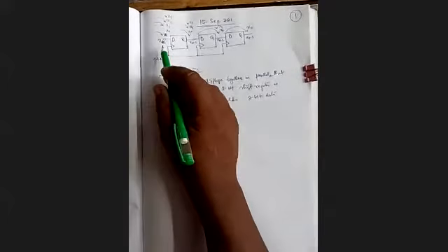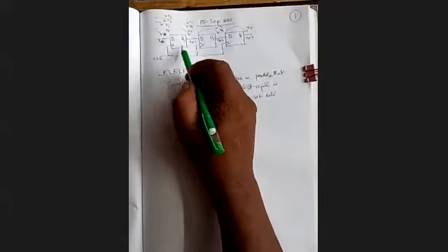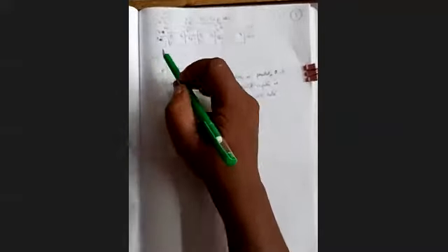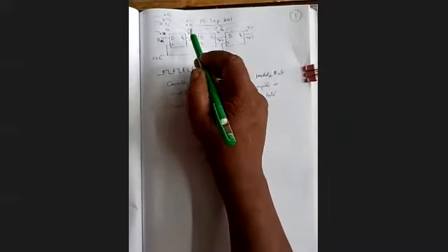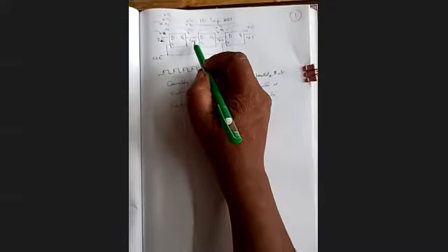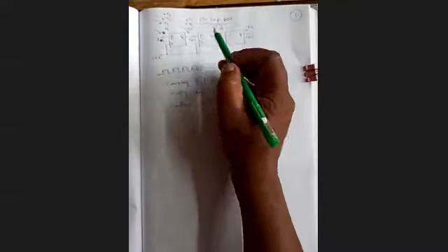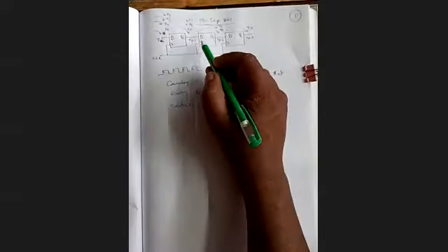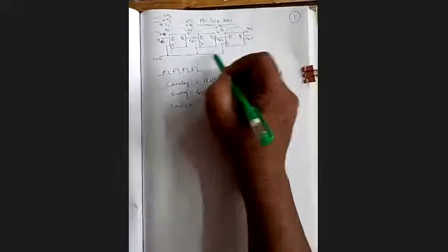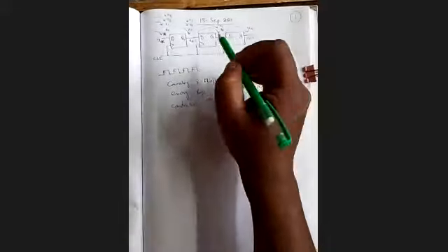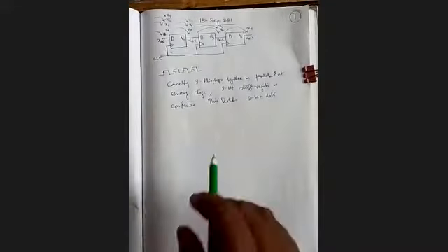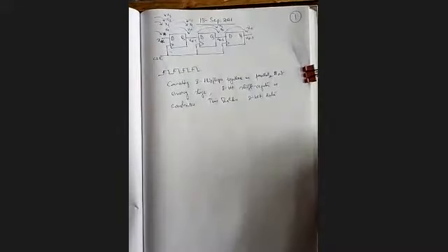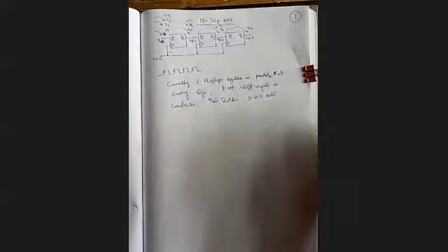So our xk will be 8-bit data, because 8 parallel flip-flops are there. Xk minus 1 is another past data of 8-bit length. It is again stored in another set of 8 flip-flops, or another shift register. The third sample is also held in another shift register this way. So at every stage we get a set of 8 flip-flops, and our shift register is constructed.